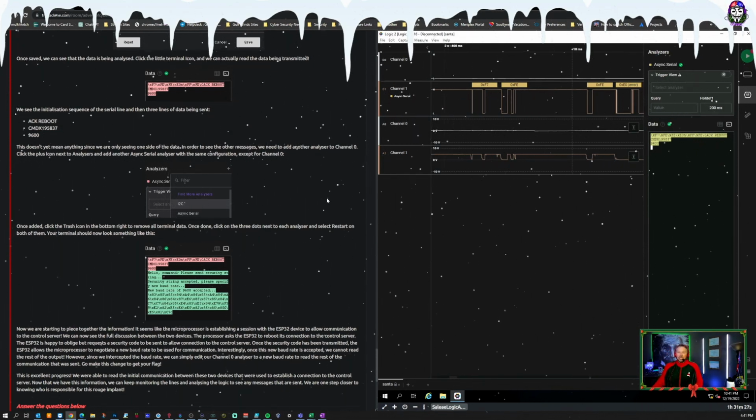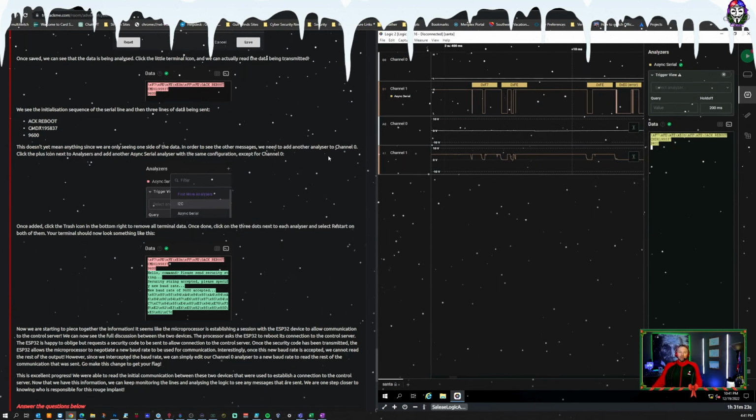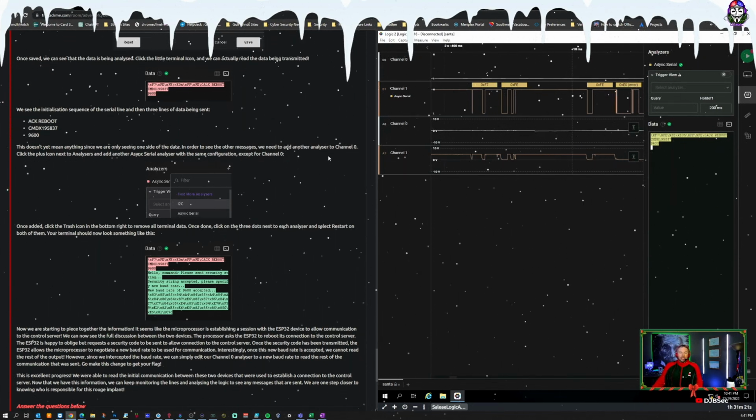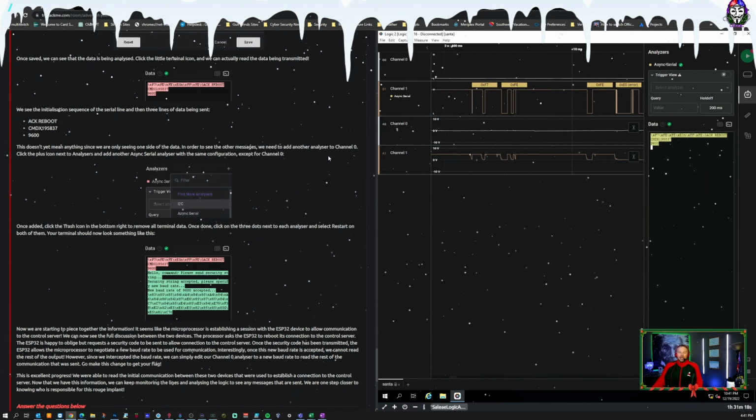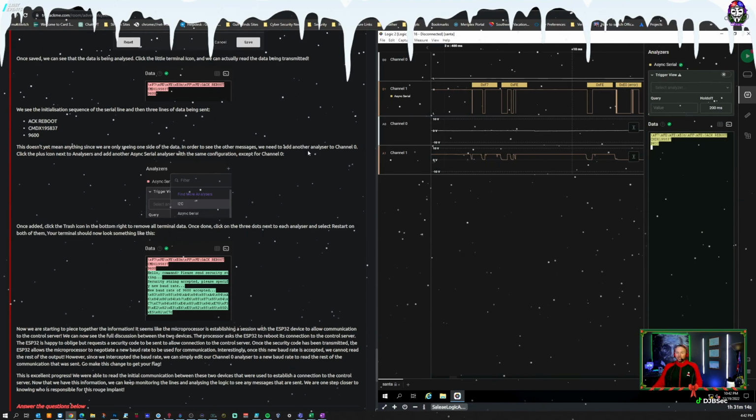In order to see the other messages, we need to add another analyzer to channel 0. Click the plus icon next to the analyzer and add another asynchronous analyzer with the same configuration except for channel 0.